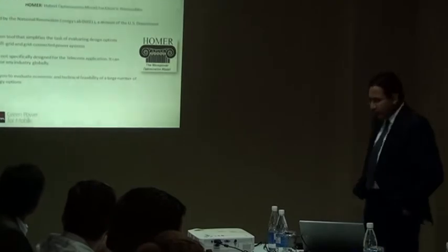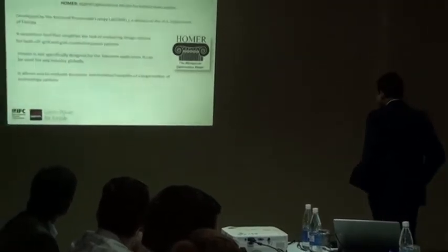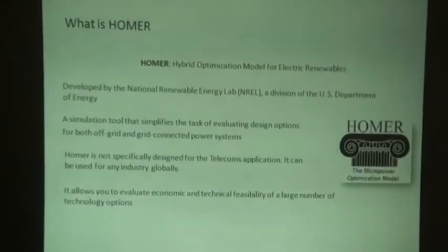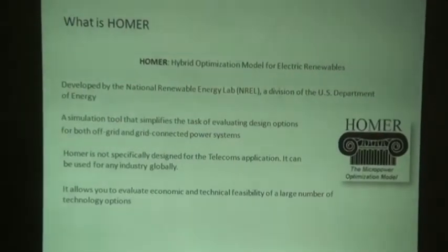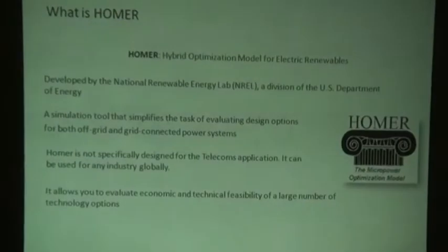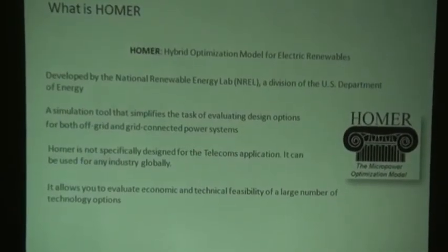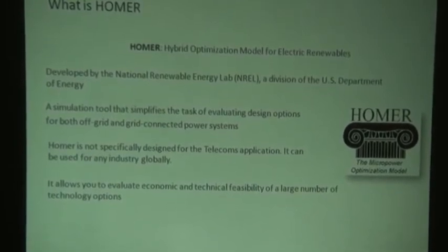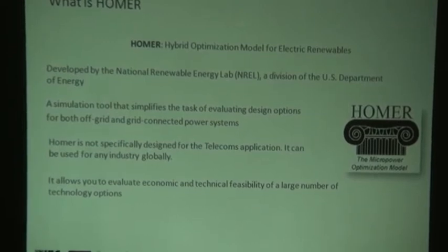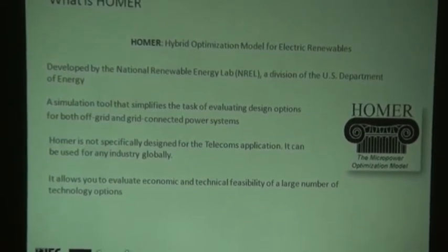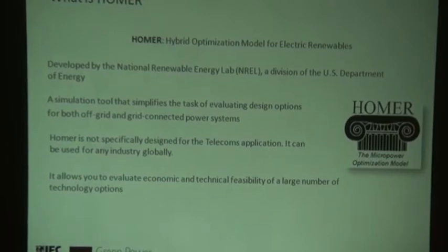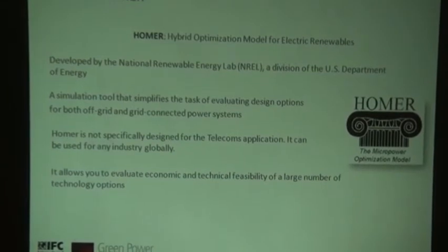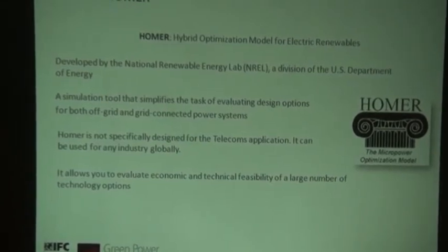Now, very briefly, HOMER is a simulation tool. It's software that gives you a very good way of creating the dimensioning of your green solution. This is one of the tools that can consider any solution: DG, battery, hybrid, grid, fuel cell, biomass, CNG based generation, wind turbine, PV, flow battery, you name it. You can incorporate all these solutions into HOMER.